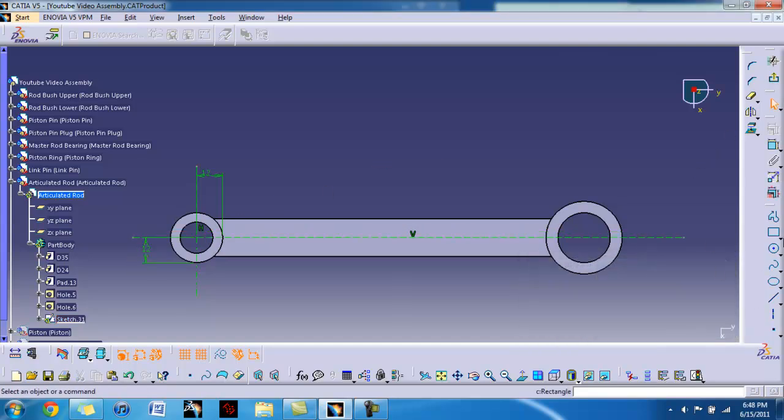Alright, the elongated hole command can be found underneath the rectangle. Select that. Make sure to click on the vertical axis. And if you tab over, you can make a radius of 5. And the length between is going to be 130. And click when it's highlighted blue, meaning it's vertical. As you can see, it can't be moved from this axis, but it can still be moved side to side.